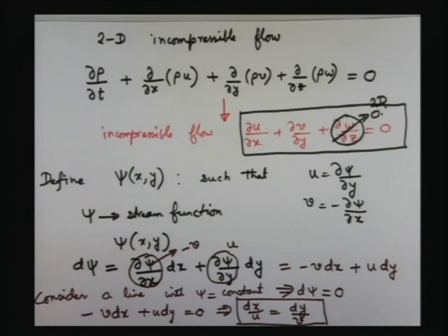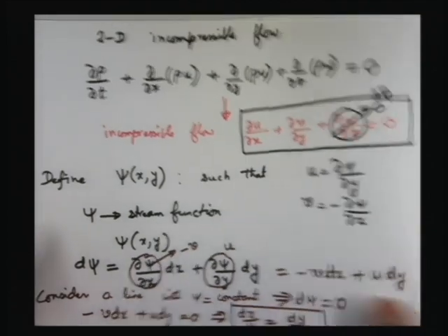That means you have two-dimensional incompressible flow where stream function is defined, and then the constant value of the stream function represents a streamline. At the end, the stream function is a mathematical function that parameterizes the continuity equation for two-dimensional incompressible flow. That is its mathematical relevance.